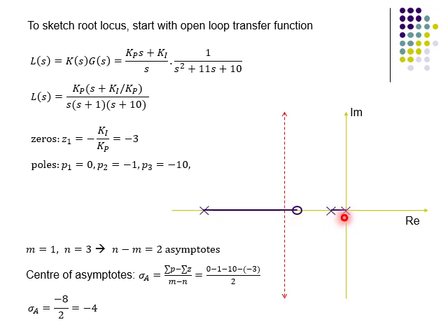So as we've got two poles next to each other here, with the locus between the two poles, we must have a breakaway point between the two poles here, and then one branch which breaks away upwards will tend to the asymptote at the top, and then the other branch which breaks away downwards will tend to the other asymptote that goes vertically down.